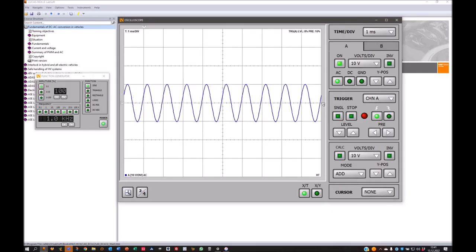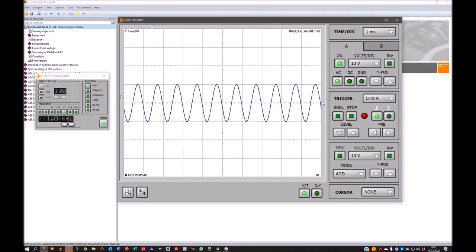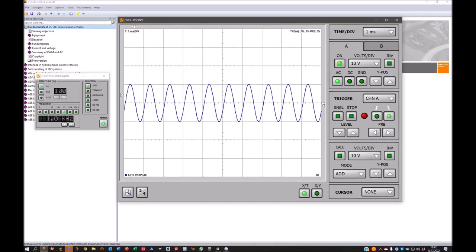So this is just the trigger now, where you can change the X and the Y position. Basically what we do now, we can say we go here and we go here. So now the trigger will be set to here as we are on a rising edge. When we go to falling edge, you will see it jumps over here to the falling edge, pretty easy.